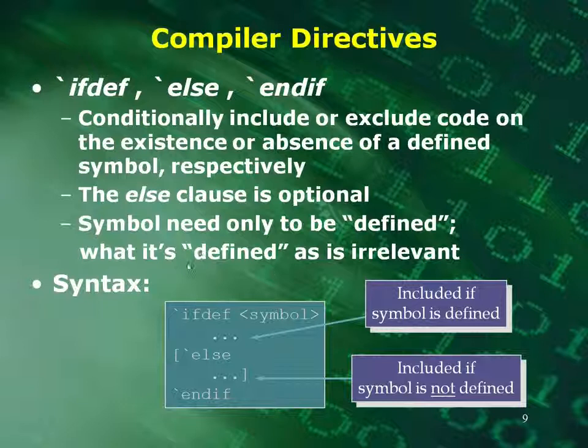Sorry, let me state that again. The symbol needs only to be defined. What it's defined as is irrelevant. In other words, if you just say `define and then some name, you don't have to put any value or any text after it. The ifdef is just wanting to know if you've defined it at all.